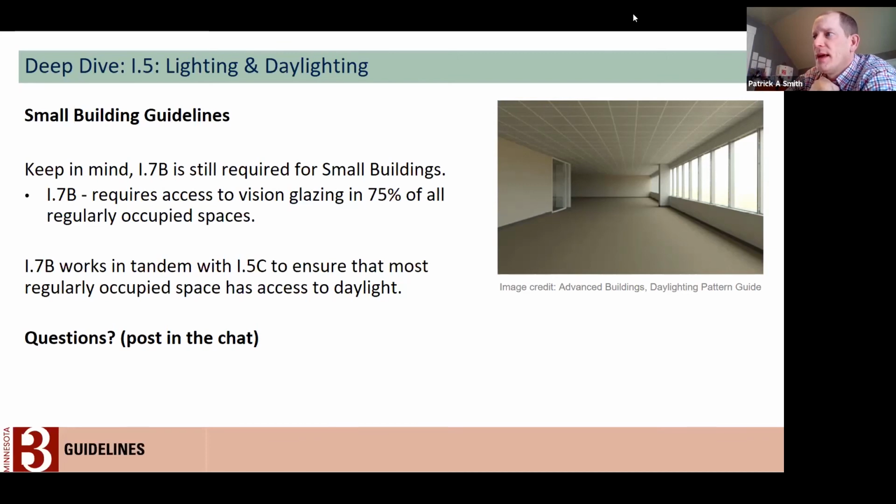We're planning on looking at the impacts of window overhangs. That is one area that you could see lower daylighting if you've got a heavily shaded window to wall ratio at 40% that we're just not picking up with this level of detail. It'd be picked up for larger buildings that you're using the daylight model, certainly, but not these smaller projects.